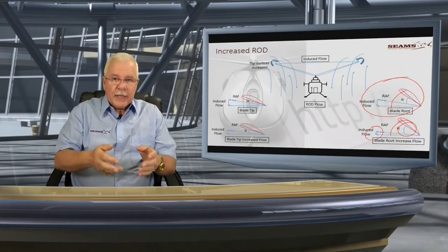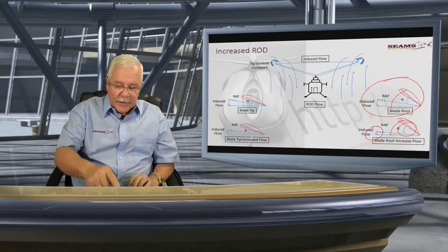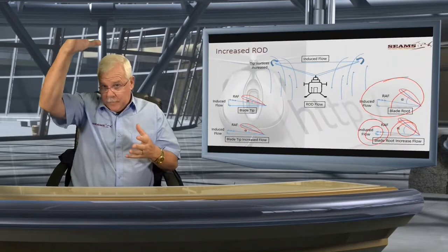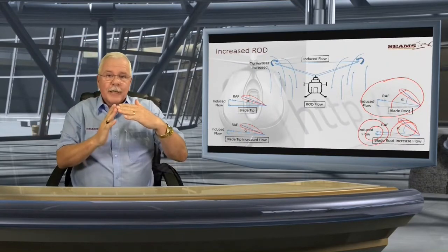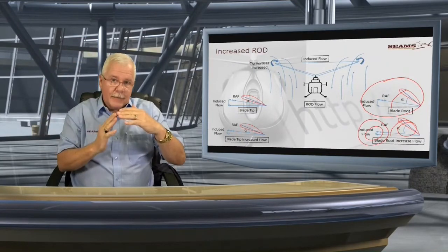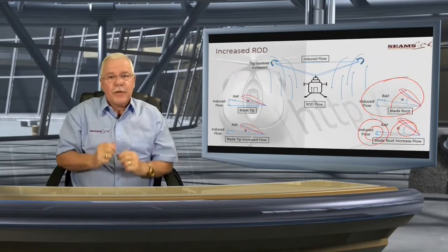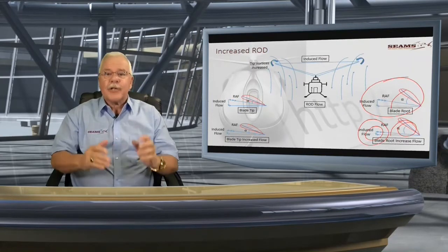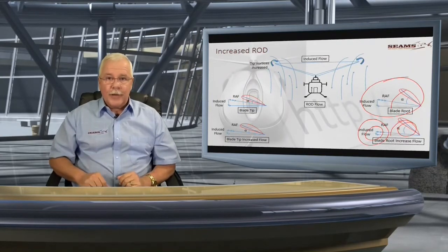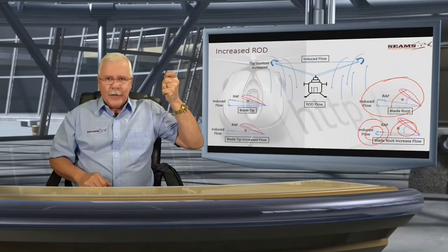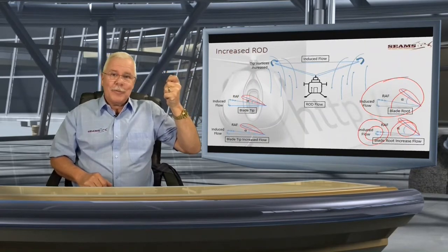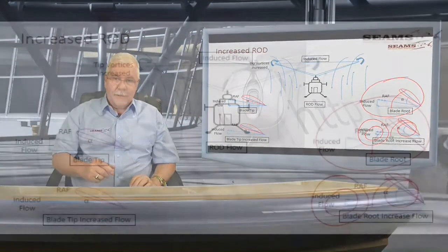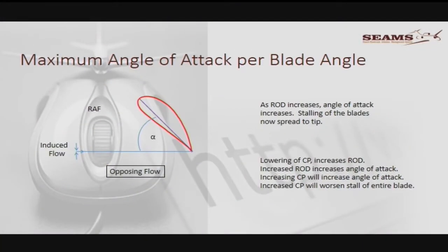Now if this is the beginning and you increase the rate further, then this induced flow through the blades that come down will be becoming less and less. The net effect will become less and less because of the opposing airflow. And therefore, the angle of attack actually increases all the time. All that you now need to do is put more power. How do you put power? You're going to pull collective. What happens when you pull collective? You're increasing the angle of attack. Voila. There you go.